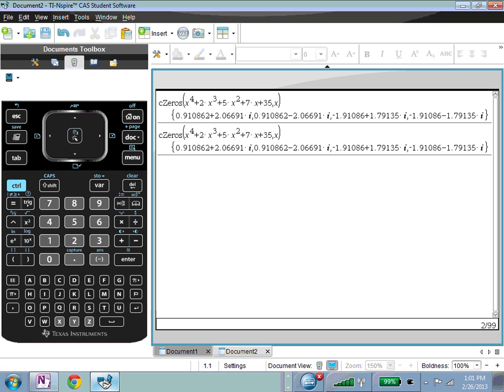So that system is not stable. But the other pair is at -2 roughly, plus and minus j 1.8. It is in the left half plane. So is my system stable? No. All it takes is one unstable root or one unstable pole to cause the whole thing to be unstable. And here I have two unstable roots. Question?